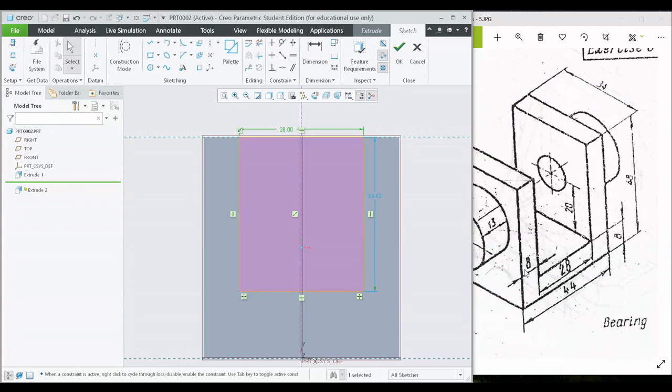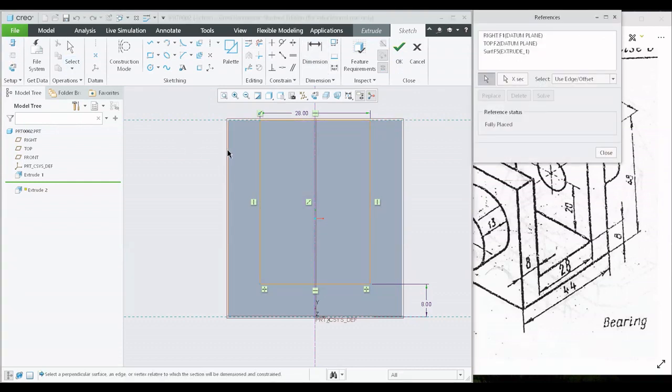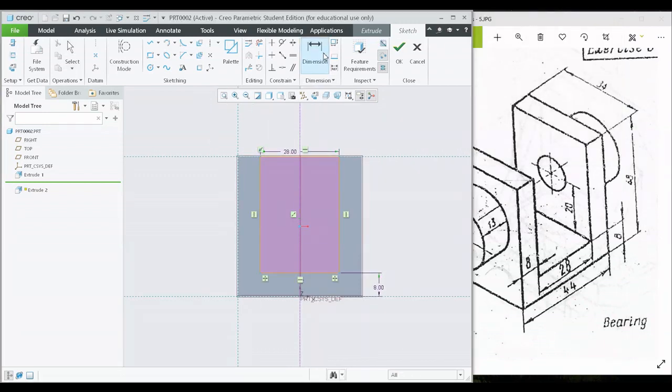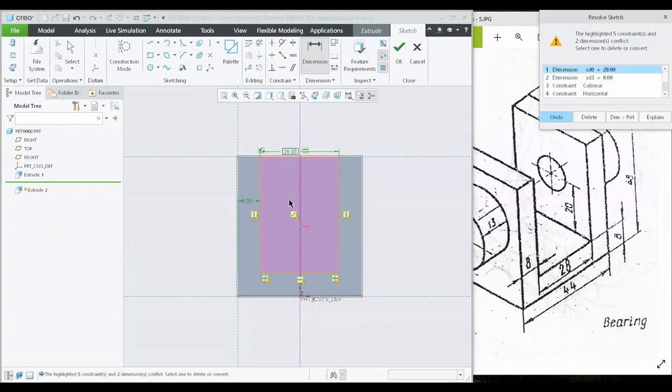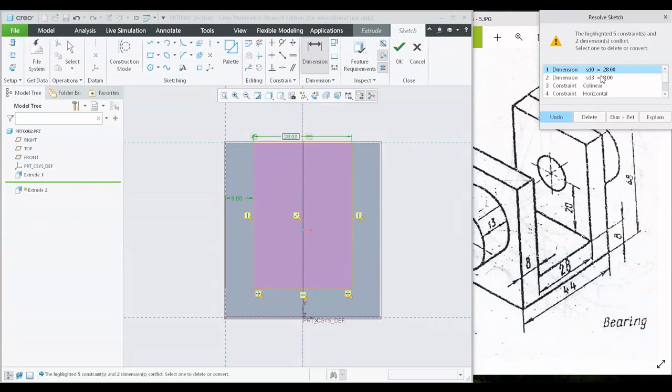So I have the base over here and the height of the base is 8 units. So I just have to click on dimensions, click on the baseline, and change the dimension to 8 units, whereas these side edges are also 8 units again. So let me click on dimension, click on the edge, and again use referencing. I recommend you to use referencing. So let me click on dimensions, the line, and the reference line, and middle click. So you get a message that this is 8 units.